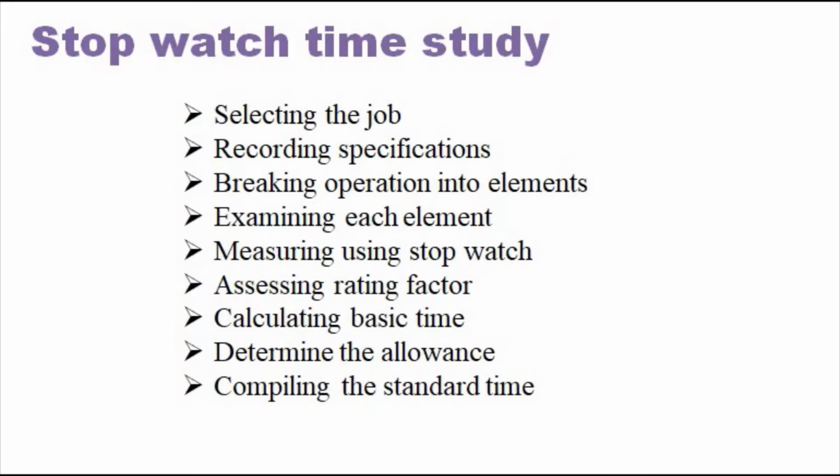One is a flyback method and another is a cumulative method. In the flyback method, once the time is recorded for the particular stage, the stopwatch is reset to zero, and then the time is recorded once again for the next part. In the cumulative method, the time is recorded cumulatively, and then the time required for each segment is subtracted accordingly. So basically there are two ways: the flyback method and the cumulative method.